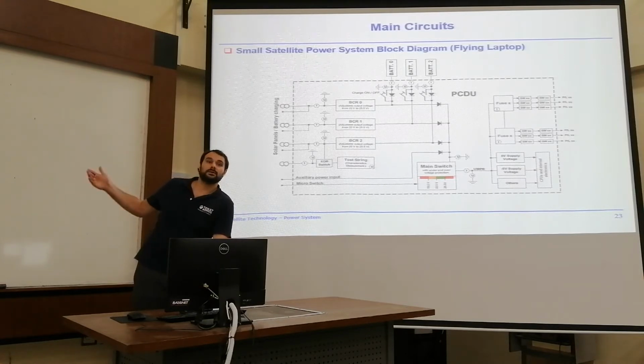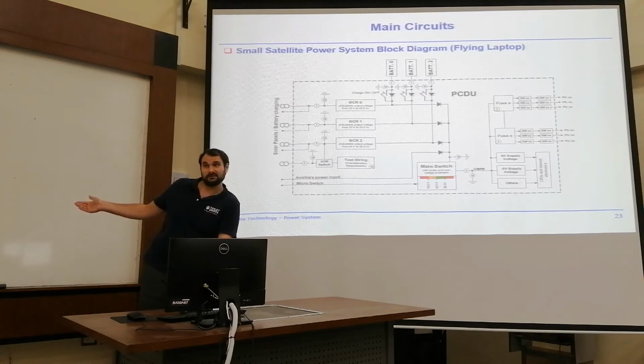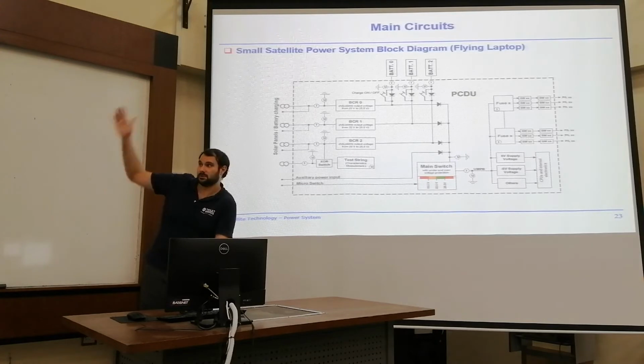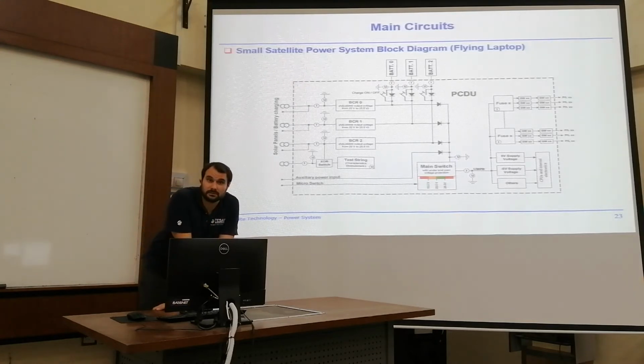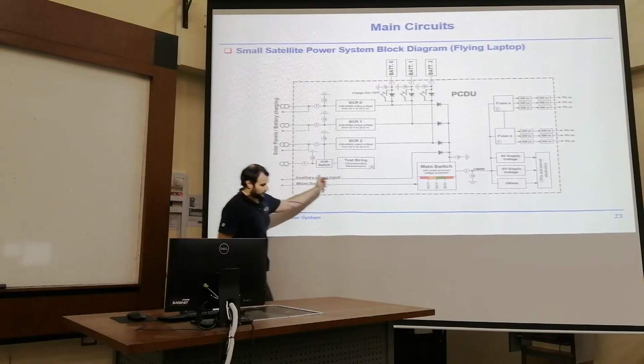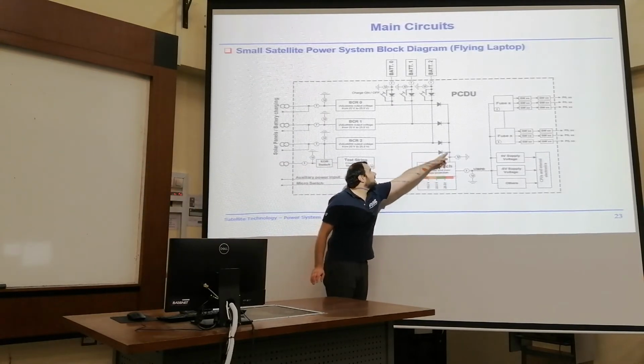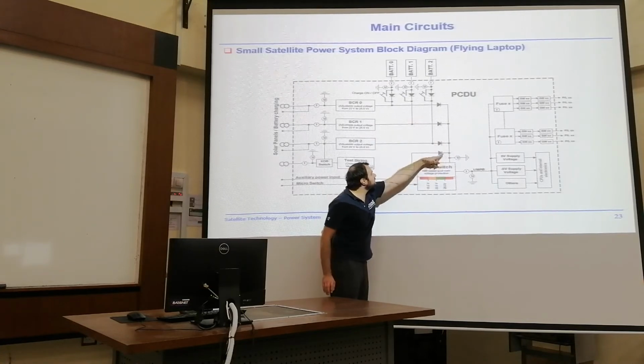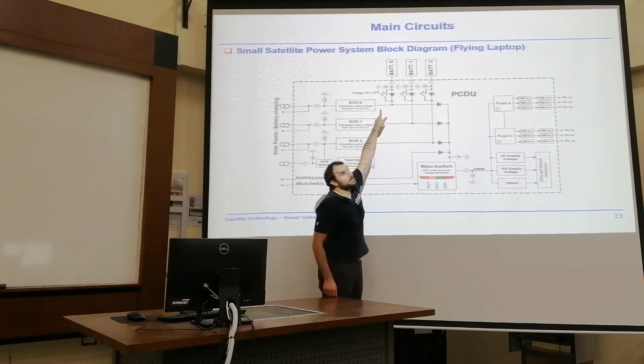That means you need to find a way to charge your batteries. I doubt that you want to bring an artificial sun into your clean room. You can do that for testing purposes, with huge lamps, which are really warm and bright. But usually, you're better off just having an auxiliary power input, feeding in here over the diode, and then if you close all the switches, from here you can directly charge the batteries.